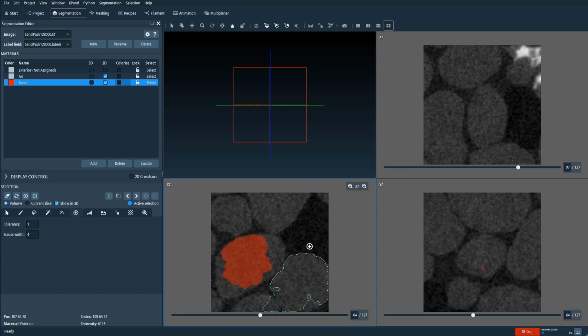So it's more strict in terms of crossing the edges. Even low intensity changes, or lower magnitude edges, would block the region growing. And the other way around, if I put in a high value for tolerance, the region grows faster and goes across the edges faster, as you can see here. So again, it's a matter of figuring out the correct value